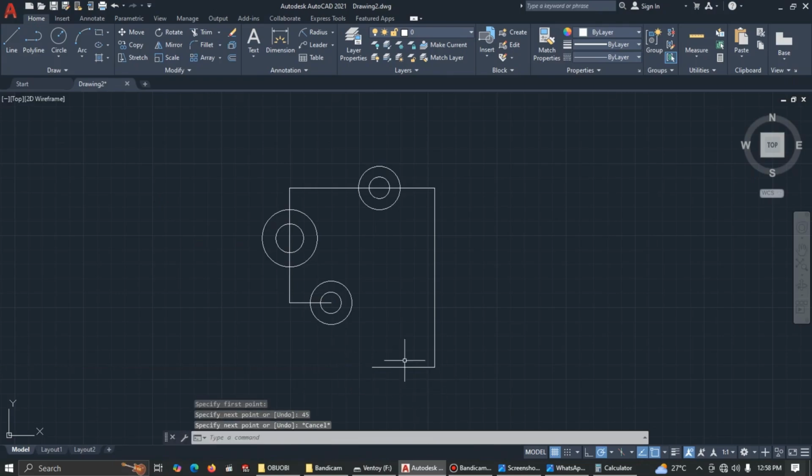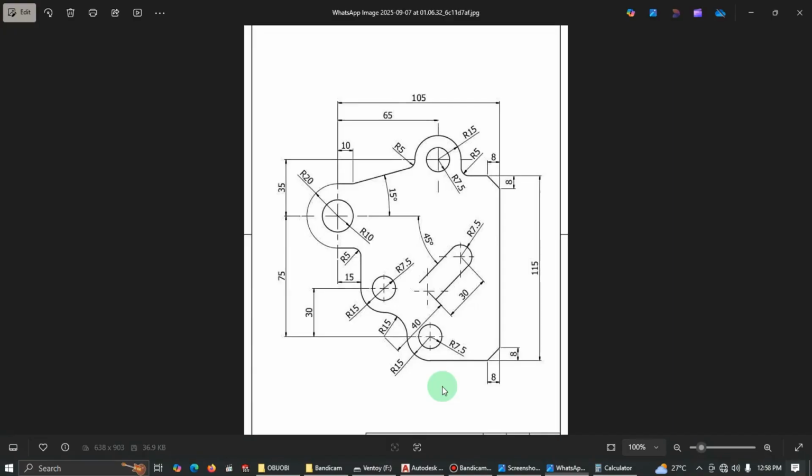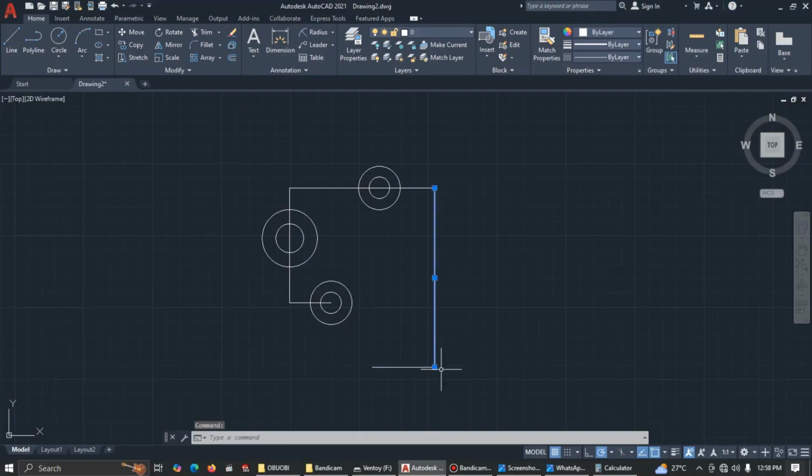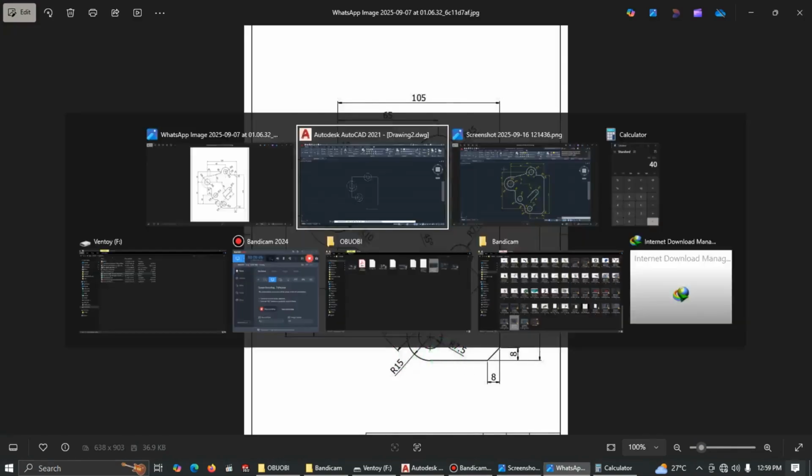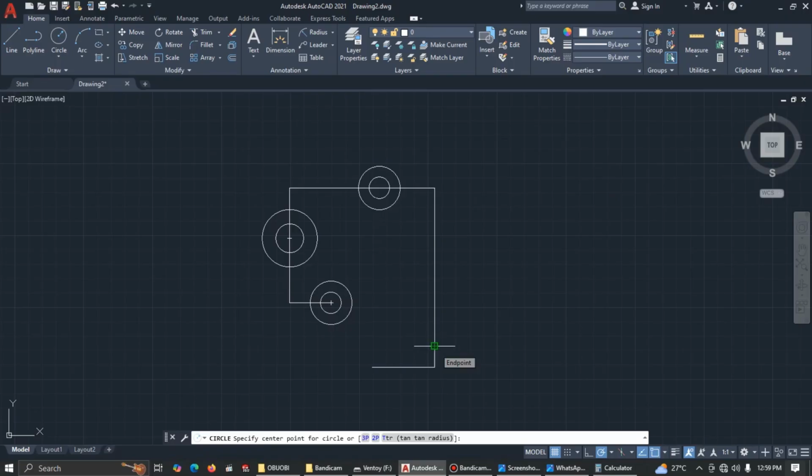Now we have to draw the circle here, and for us to get a circle here, remember we added the radius of 15, so we now need to subtract 15, then move 45, and then we get to the point here. Just select this line and select one end, move up, and then enter 15. It just adjusts itself like this. Now pick a line. You can use a line or the circle. Let me use the circle, and the radius of the circle is 15. I'll bring my cursor here, I won't click, and I'll just drag, enter 45, and then it automatically gives me the distance.